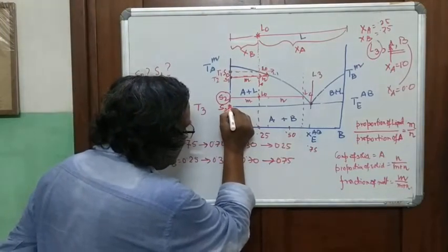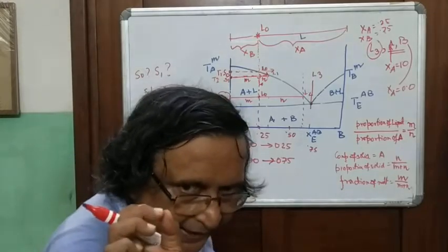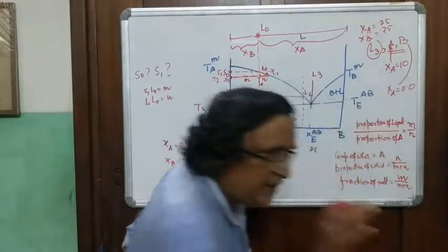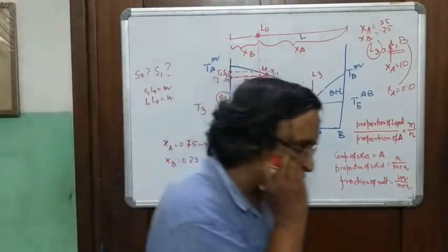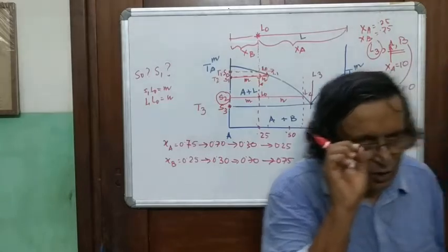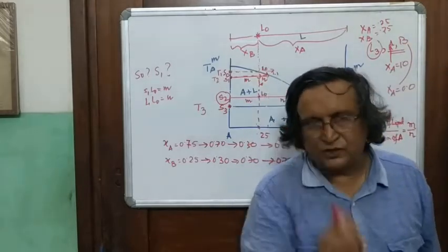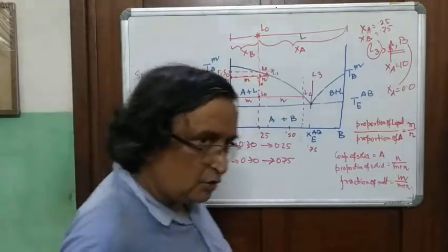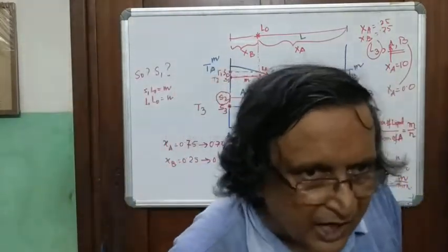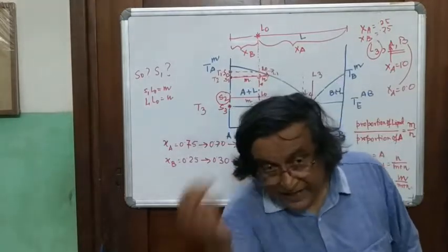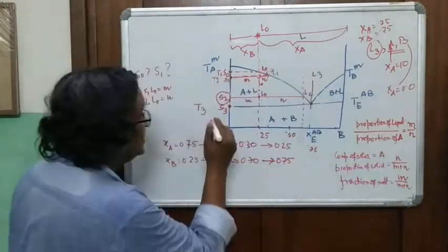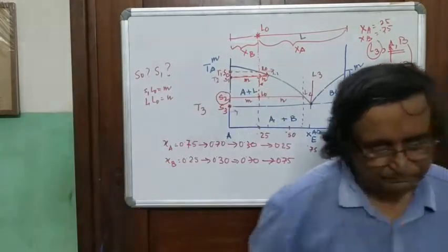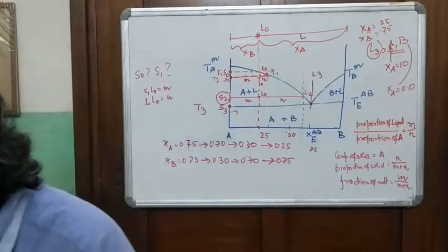Solid S3 is still pure A. But when you precipitate pure A and pure B, the solid point which marks the composition of the solid will not be able to lie on the vertical axis, yes or no? It will not be able to lie on the vertical axis because B is being added. So the solid composition will move inside the binary.